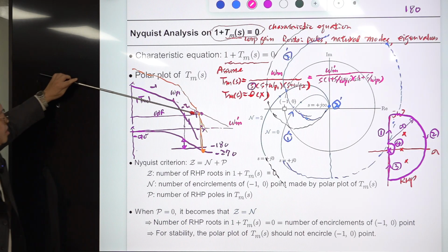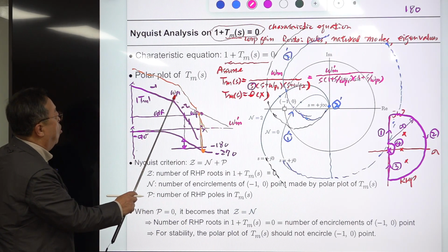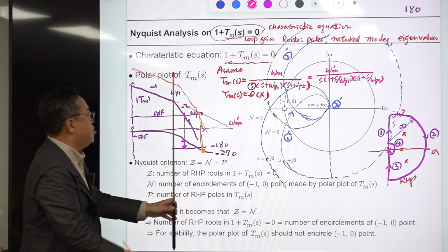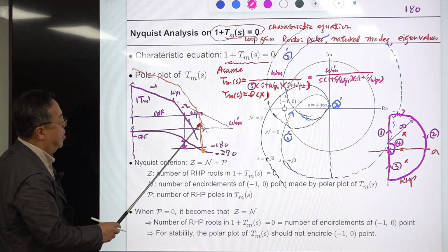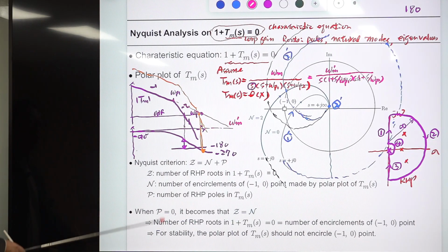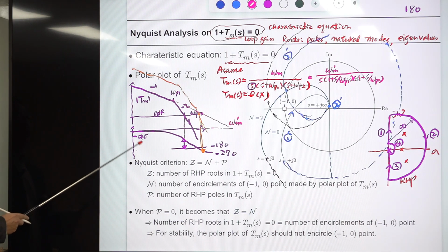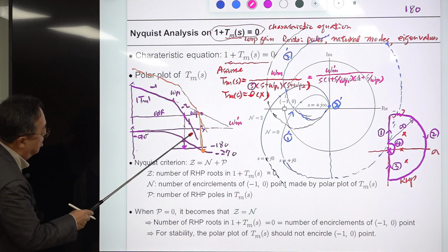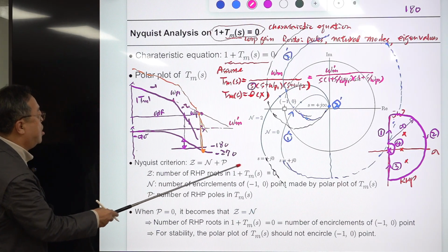So initially it starts out with this minus 1 slope, and when it hits omega p1, the slope changes to -2, and it has another pole, omega p2. Then the slope changes to -3, and the phase characteristic is shown here because the initial slope is -1. The initial phase is -90 degrees, and the phase will decrease, and eventually it will arrive at -270 degrees.